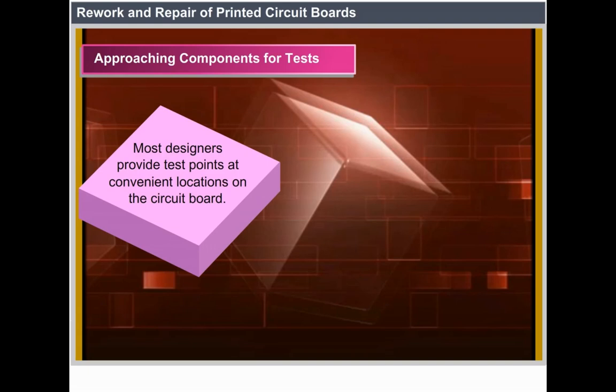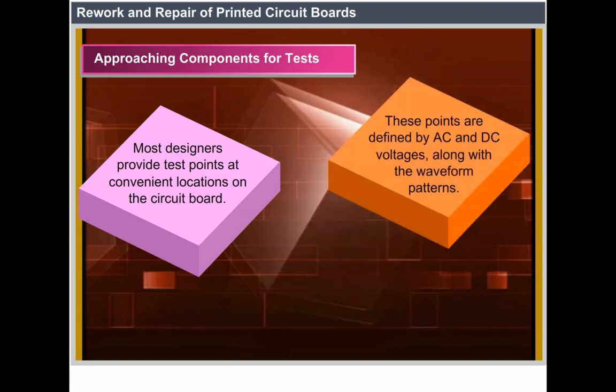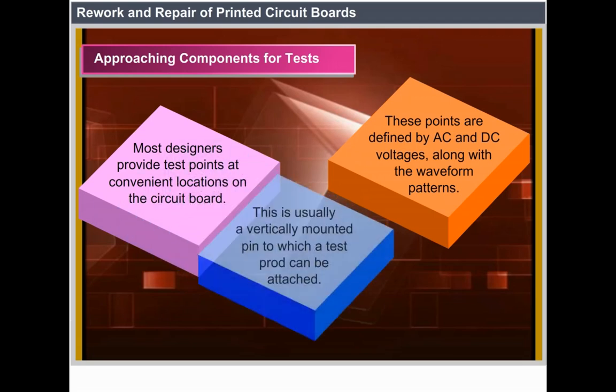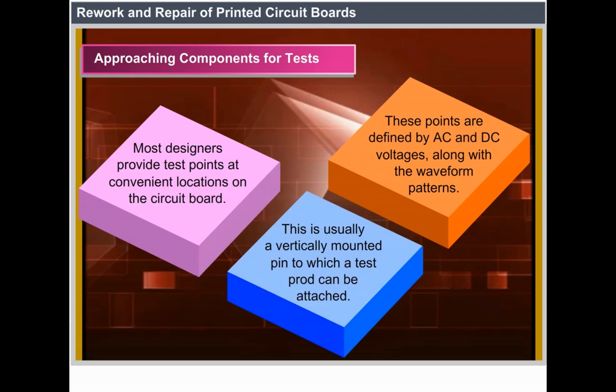Approaching components for tests. Most designers provide test points at convenient locations on the circuit board. These points are defined by AC and DC voltages along with the waveform patterns. This is usually a vertically mounted pin to which a test prod can be attached.